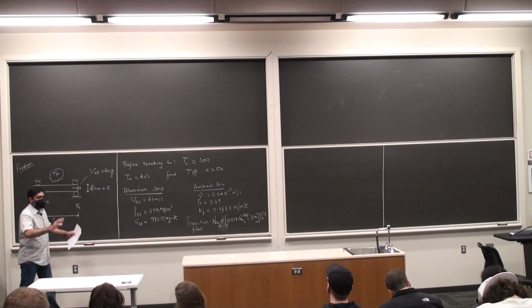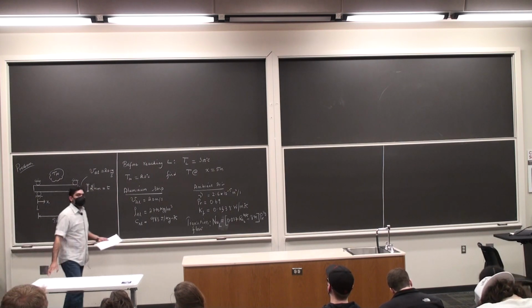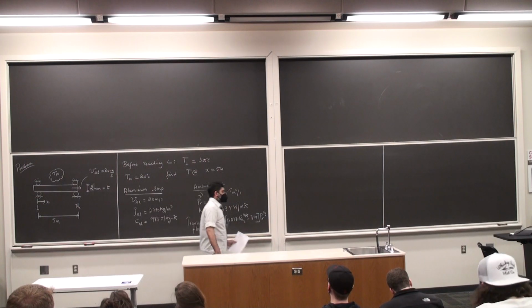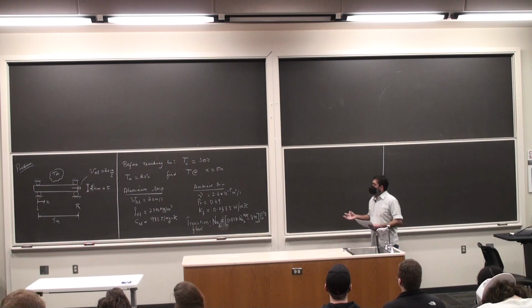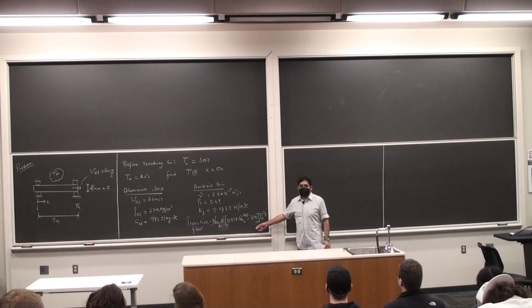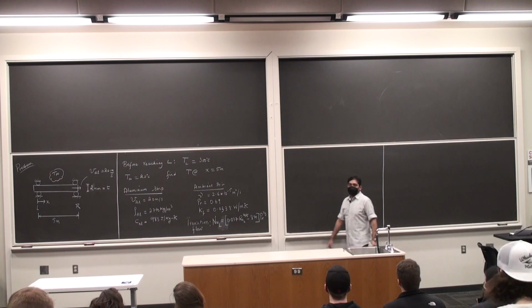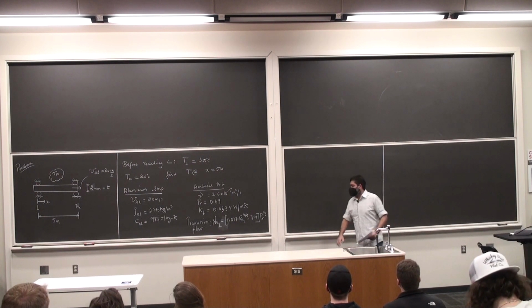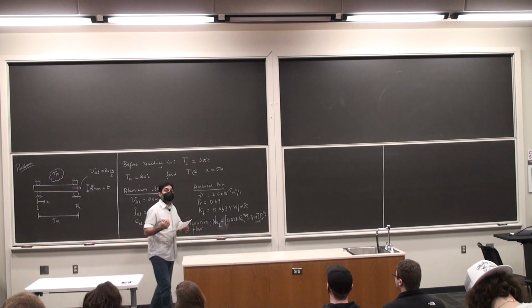And let me tell you, even though we are looking at flat plate problems, take any type of external flow, flow past a cylinder. You're going to have probably a sufficient wake region and so on. But the idea is the same. If I am given the local or the average Nusselt number, I can calculate the convective heat flux. Even if it is internal flow, makes no difference to us. The transition from laminar to turbulent is different in internal flow.